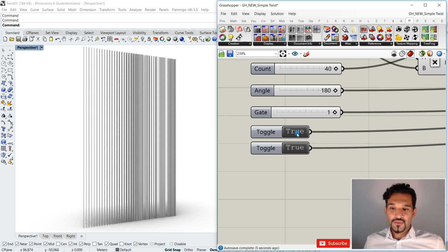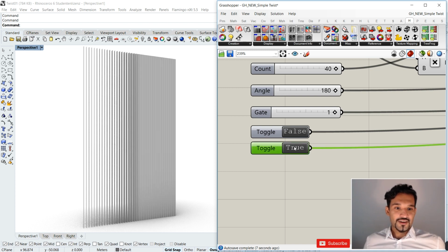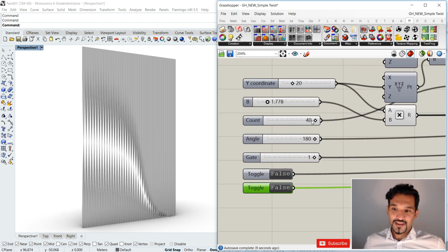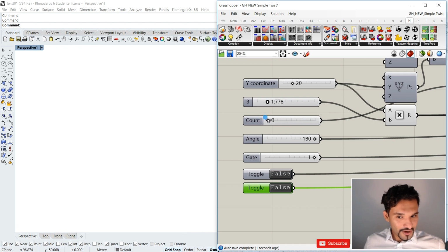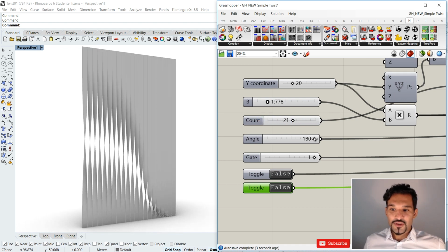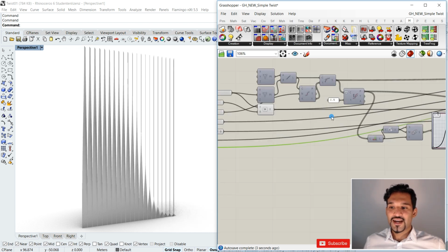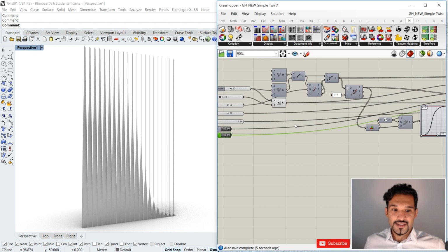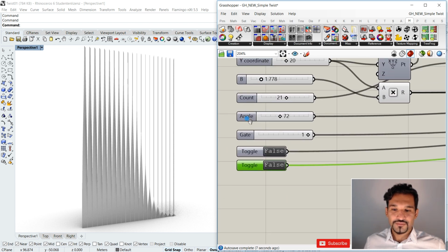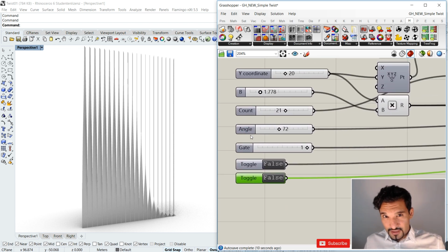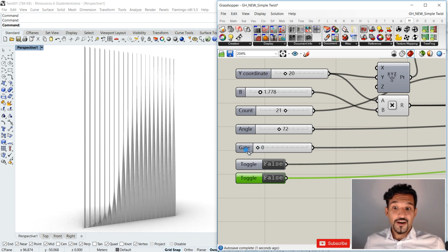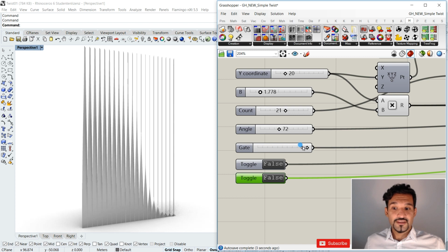We came through. So if I go back, we have our stripes. We just generated our stripes, very, very straightforward. Then we used our rotation and our twist command. We looked at how to use the graph mapper to actually generate some geometries, a different kind of underlying logic to it. We looked at how to reverse those graphs just by reversing the numeric values.